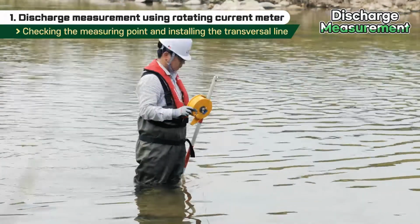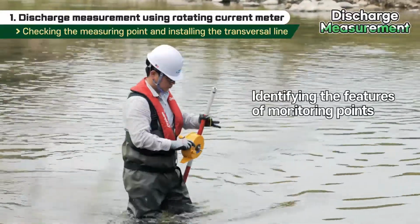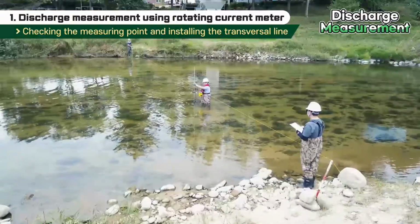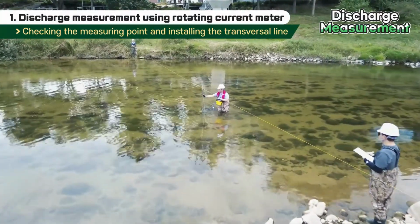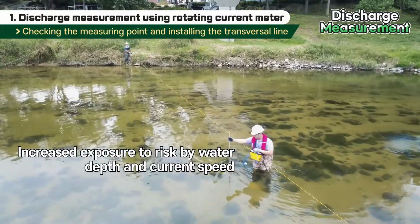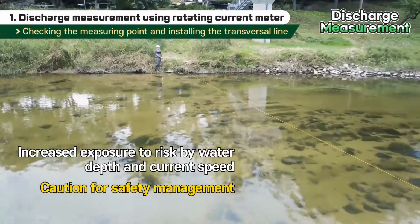The first thing to do on site when taking the current measurement is always to identify the features of the monitoring points. Wading measurement is a method by which the on-site worker directly enters a river. Because it is risky due to exposure to water depth, current speed, etc., the measuring points should be carefully selected with safety management as a priority.